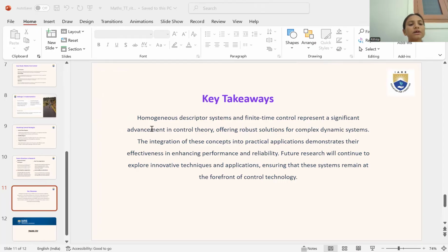Homogeneous descriptor systems and homogeneity-based finite time control of a linear descriptor system. The homogeneity property can be verified algebraically, as for systems described by ordinary differential equations. It implies scalability of solutions. A finite time stabilizing feedback control is designed for linear descriptor systems. The proposed control contains a homogeneous linear feedback term and a non-linear homogeneous stabilizing term. The parameter tuning is presented in the form of linear matrix equations and inequalities. Performance of the approach is illustrated by numerical examples.